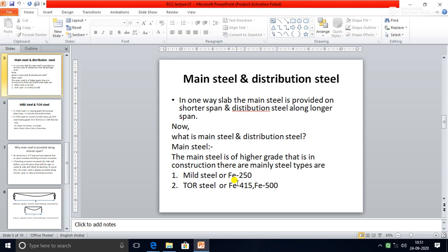So you have to remember, for a particular design, that is design of one-way or two-way slab, the main steel is 8 mm, 10 mm, 12 mm, 16 mm, 20 mm and onwards. Likewise, the distribution steel is only 6 mm or 8 mm. In particular cases, 10 mm bars are also used as distribution bars. You follow this? This is very important for our study.